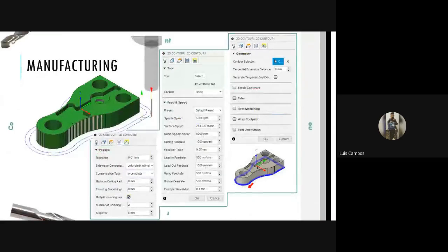And now the final step is on the setup stock, a box was selected. So there's still material that needs to be removed. And since it's around the stock, the operation needed is a contour operation. And here the tool selected was the biggest one, Fusion first, so it can remove more material.